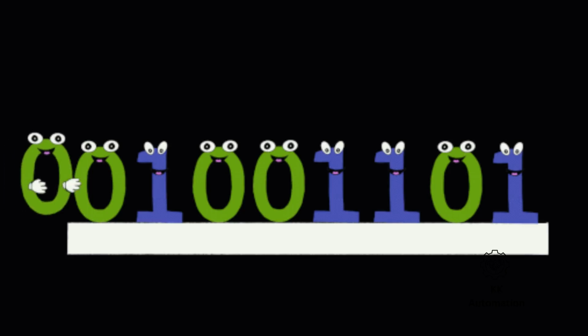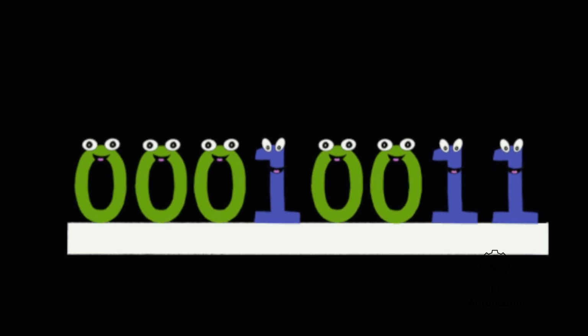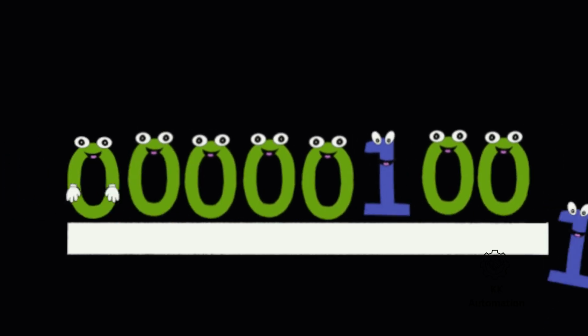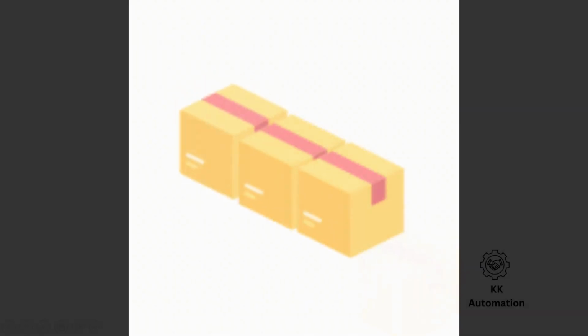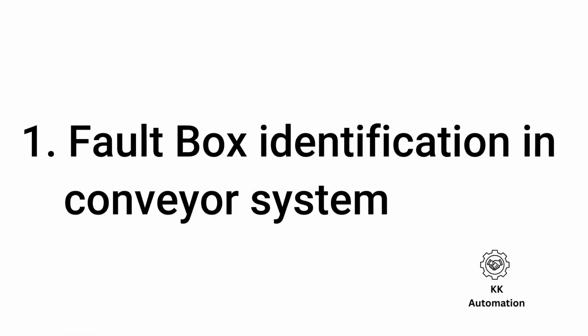So, why are these functions so important? Let's look at two key examples. Application 1, the digital conveyor belt. Imagine a production line with 16 steps. Some work pieces are green and need special treatment, while others aren't. We can represent this with a 16-bit word, where a 1 means the piece is green and a 0 means it's not. As the conveyor belt moves one step, we simply shift our bits one position.